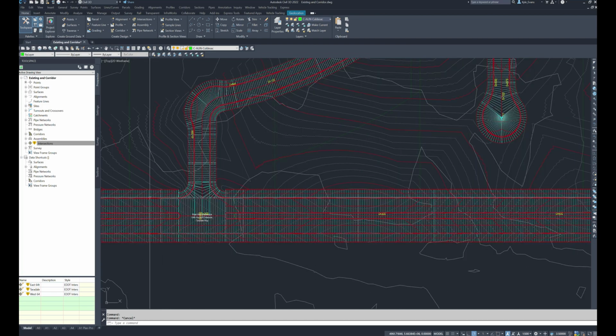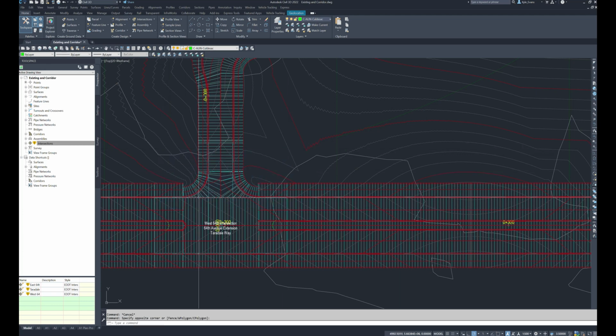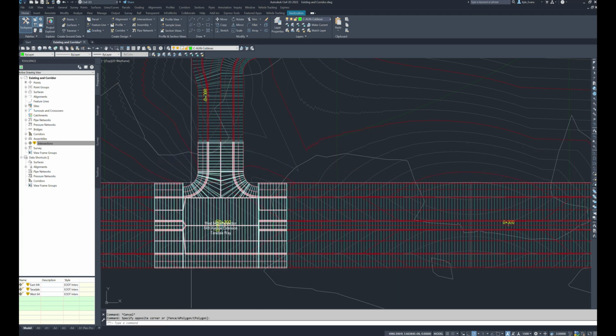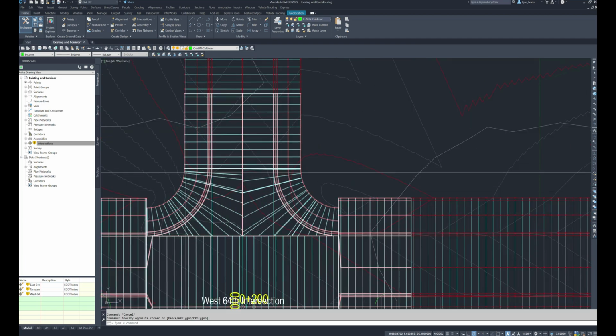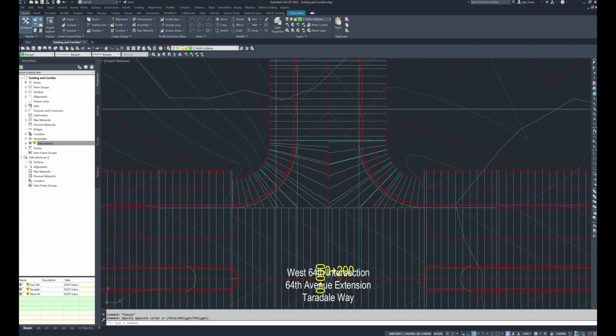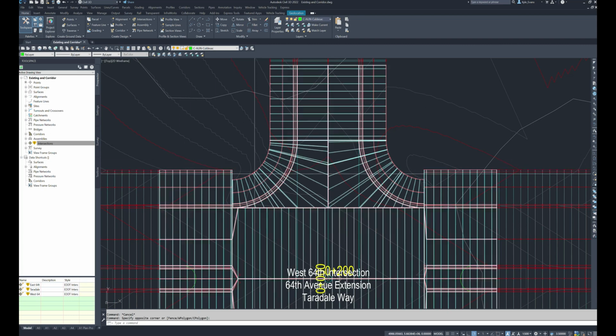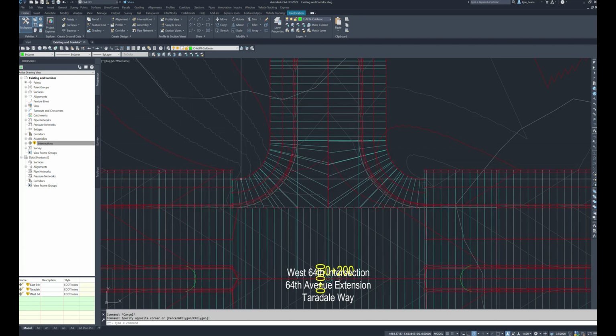And also if we have time, we're going to play with some additional targeting options in order to have our residential road and our primary collector line up for the sidewalk offsets and locate those sidewalks properly. We'll probably end up using feature lines for those.